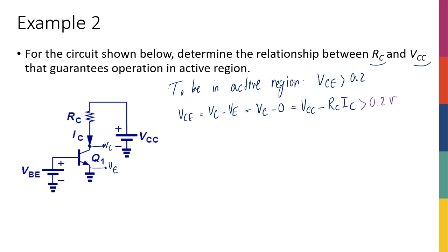I just want to remind you of something very interesting. Remember that when I was talking about the biasing of transistors and this exponential relation between VBE, the base emitter voltage, and the collector current, and when we were talking about GM, I was saying that I want my point of operation to be at a certain part of this curve that has a higher slope, right?